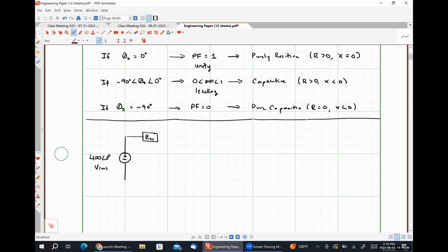This is what's going to be known as a line impedance. So it represents the characteristic impedance of transmission lines. This is typically pretty small and slightly inductive. So let's call this 0.01 plus J 0.05 ohms.